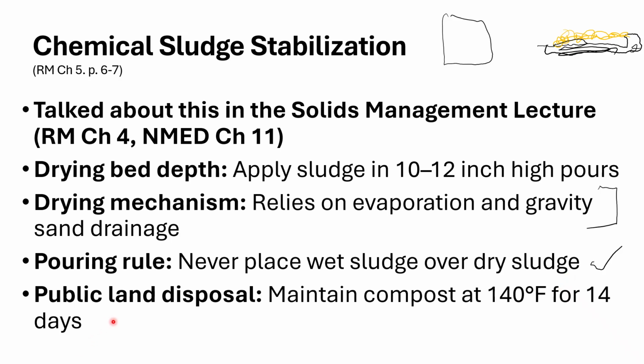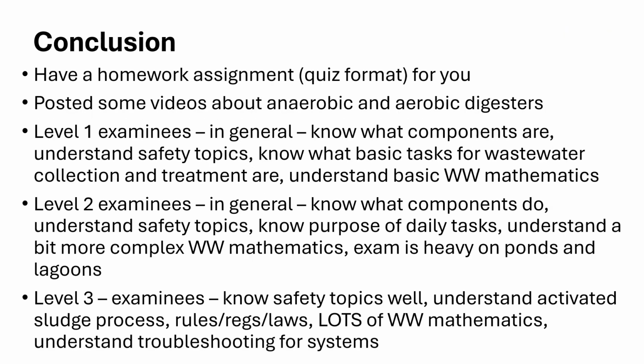That's a legal requirement, okay? Maintain the compost, that dried sludge, at 140 degrees Fahrenheit for 14 days. That's an important rule of thumb, okay? That's the material we have for this chapter, chapter 11 in the Environment Department Study Guide, chapter 5 in the Ragsdale Manual.